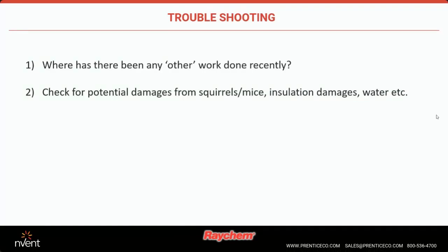Secondly, checking for any potential damages that are visual is the best, quickest means if you have access to look at the cables. I have had, unfortunately, squirrels and mice and birds get into cables, and if they can chew, they will chew. So that's been a potential problem. Insulation damage. If the insulation is not a water resistant type, and water does get into the insulation, it will render that insulation useless.